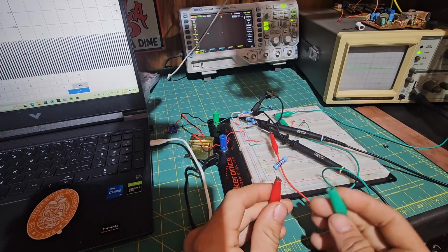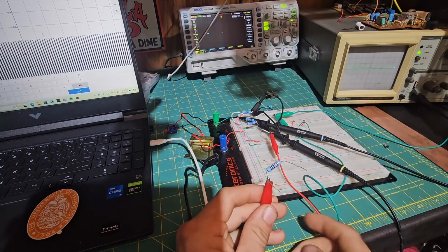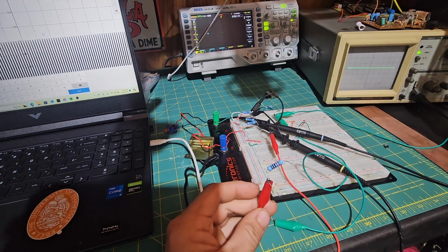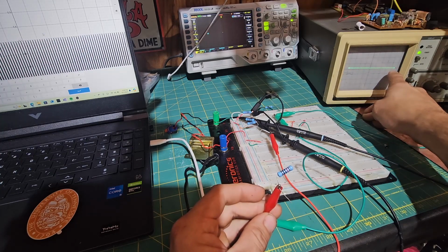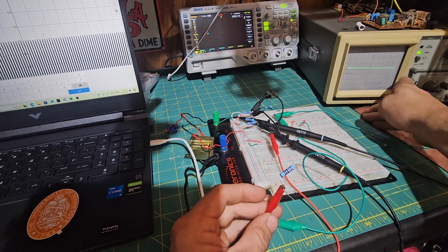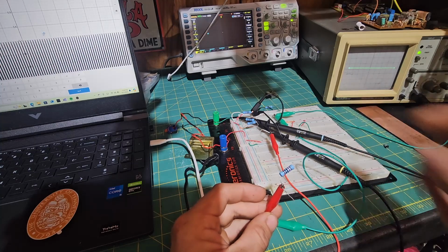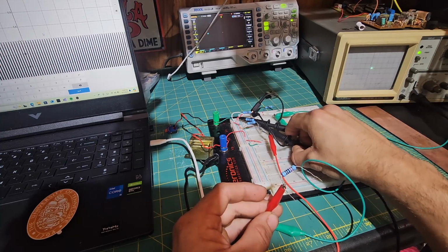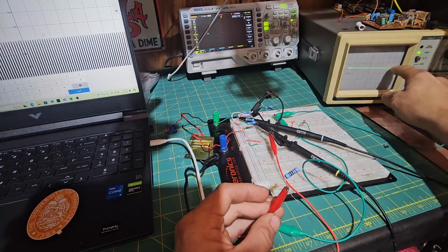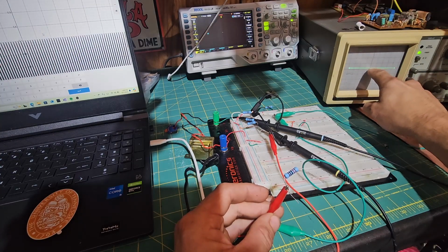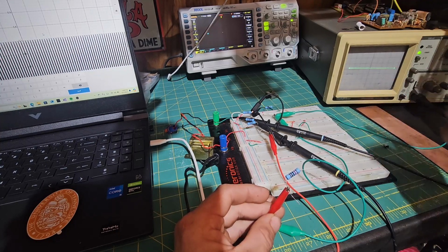So I have these two test probes right here, and this oscilloscope is just drawing a horizontal line right now. What's actually happening is the x-axis on this oscilloscope is no longer time. The x-axis of this scope is now being driven by this input, by this probe right here. So you can see if I remove it, it just goes to a dot. And what it's drawing right now is an AC voltage. So the beam is constantly moving from the center where the dot was out to this end at one peak, and then it's coming back, moving out to this end at another peak.